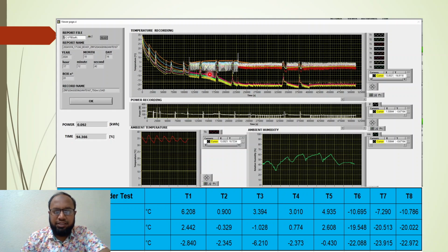After this time the refrigerator is not cycling yet, because the refrigerator chamber temperature is not reached, but the freezer chamber temperature is reached. After the freezer chamber temperature is reached, the curve goes up and down, because the damper is sometimes on, sometimes off, sometimes open, sometimes closed, as it achieves the temperature.